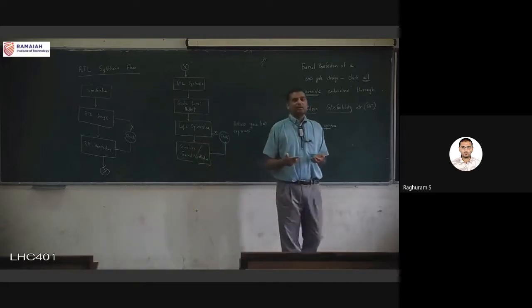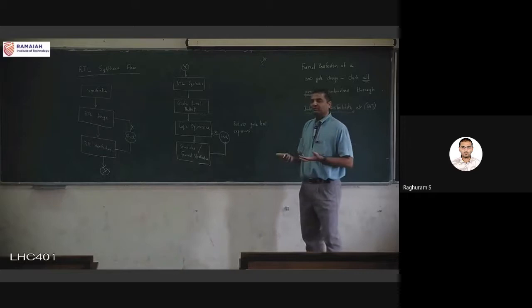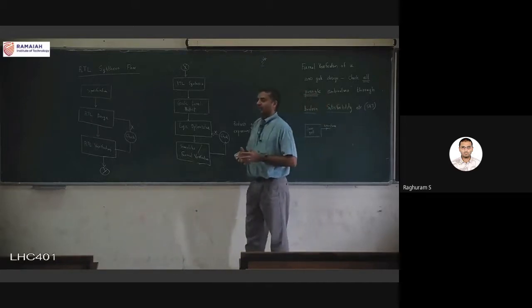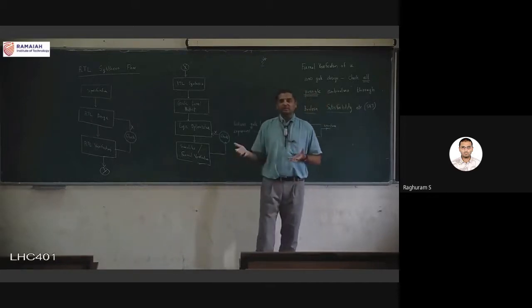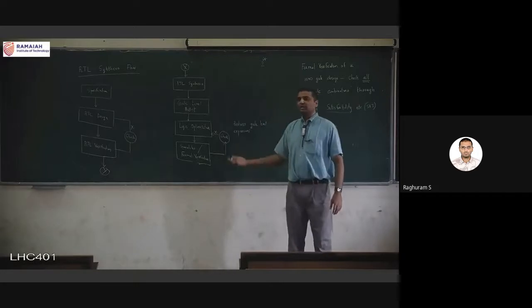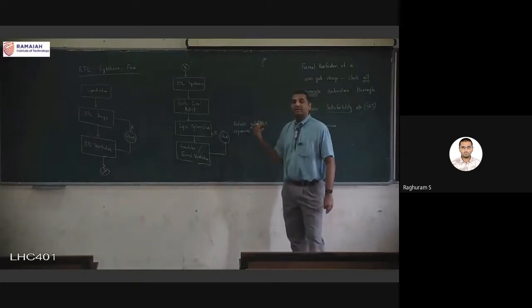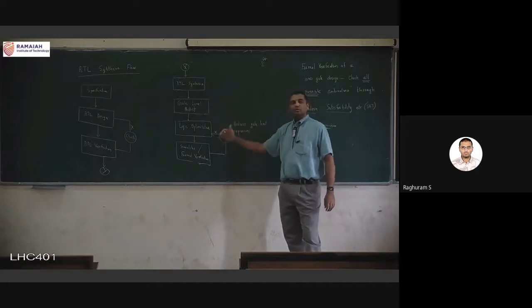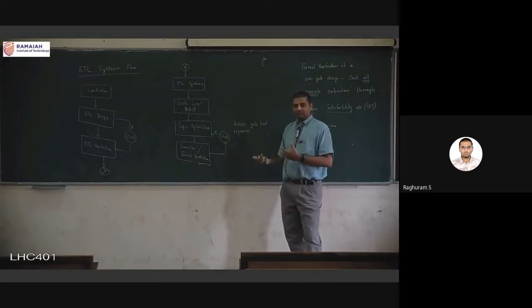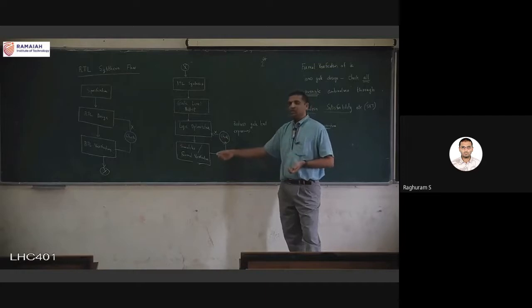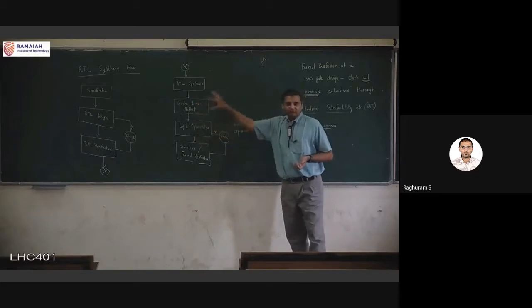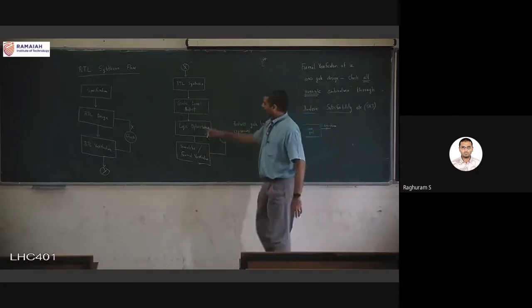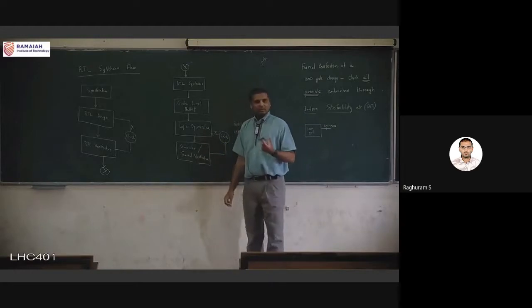Of course, the tools, as far as possible, will try to maintain the functionality, but because these designs are so large, something could happen where the functionality is misunderstood or lost. That is why it's important to check after every transformation. And verification is the majority of the time, 70% of the time in the VLSI design flow. So after this, we are sure that the logic is fine.